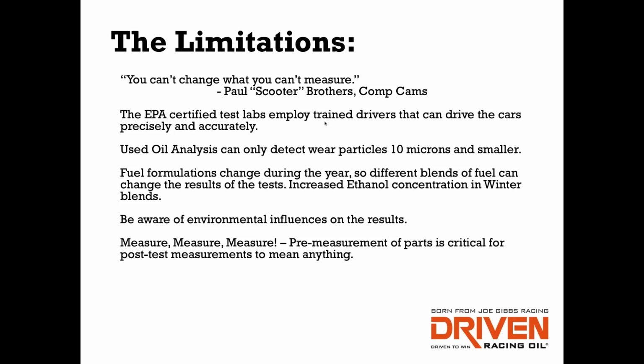Not to say that if you can see it, you shouldn't have the samples done, but just be aware of the limitation: your eye can see particles that are about 40 microns and larger, and the analysis can't see those. The benefit of used oil analysis is that it sees the stuff you can't see with your eye.